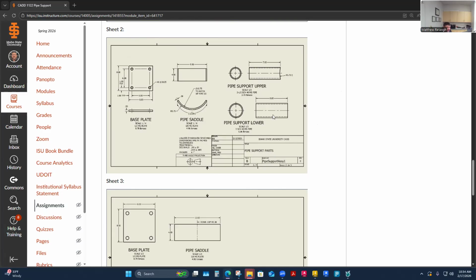This also shows the other thing you have in prefab a lot, which is saw cut items. These prefab people are cutting laser parts, plasma parts, rolling, press braking, and sometimes just saw cutting parts to blank lengths. Then they might even be doing the cope on them if they have a coping machine set up. Coping machines almost look like a side mount end mill, like a machinist tool, made for coping pipe.